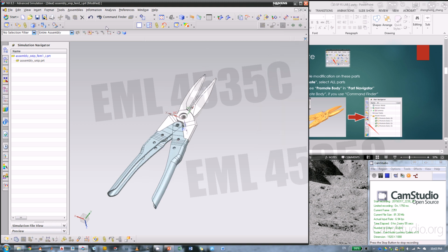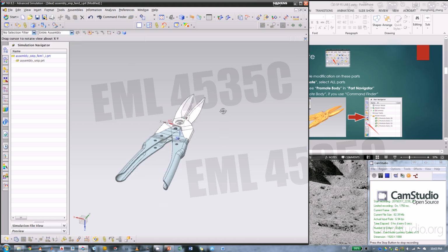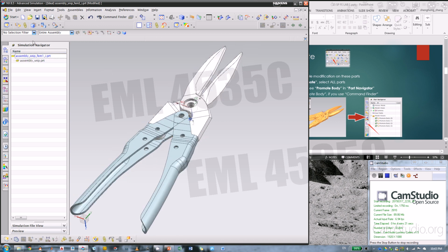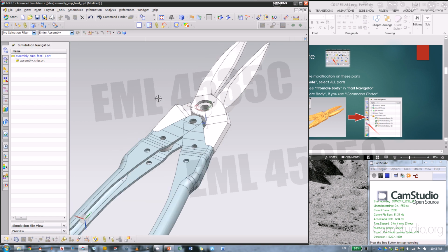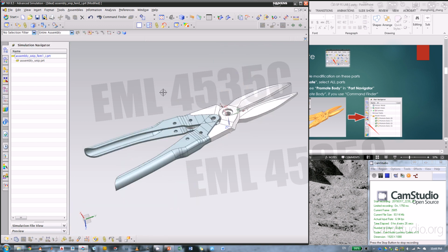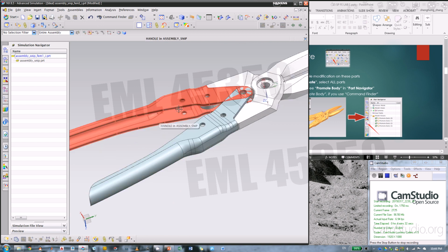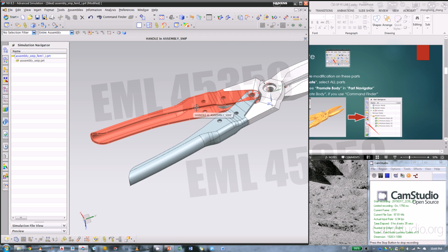Alright, then once we're in the idealized part, first thing you need to do is promote. So for now, this is one gigantic piece of CAD. There's no information on a single part. You cannot modify it. This idealized part is considered as a whole piece. So if we want to do some modification, you need to promote the body. And why do we need to modify it? You might have heard what Dr. Zarda said in the class, that this is a shell-like structure.